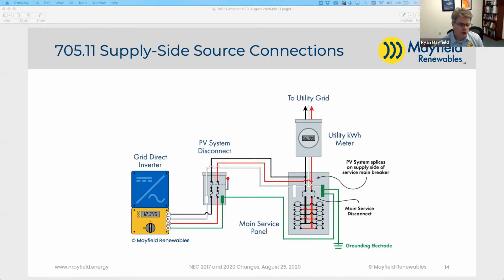How hard are those inverters being run? For how long are they putting out the full current? If it's a 1.5 to 1 inverter loading ratio, then they're going to be operating probably at 9, 10 o'clock in the morning, putting out full output current. And then by noon, when it's really warm, or 2, 3 o'clock in the afternoon, those breakers are going to be really hot.